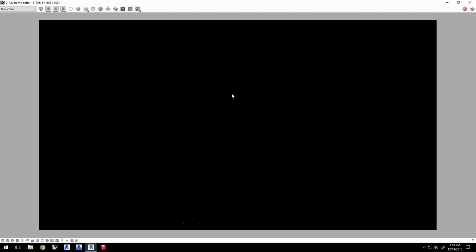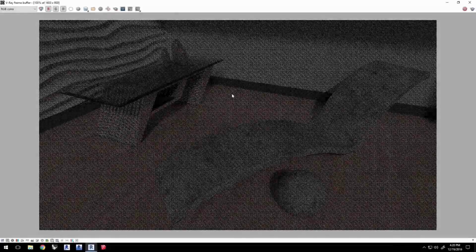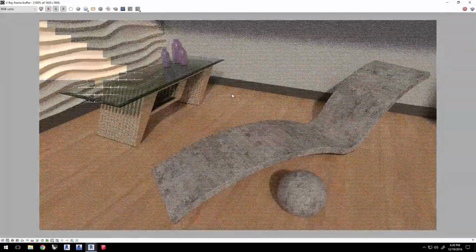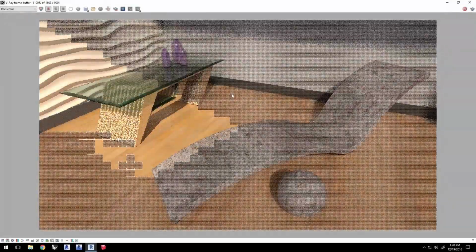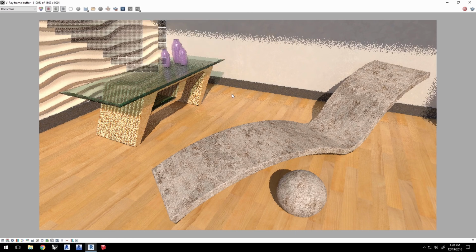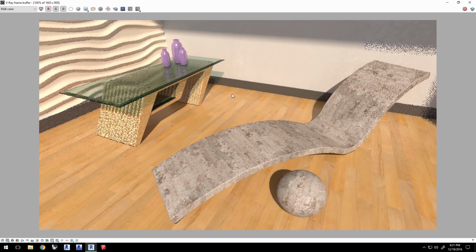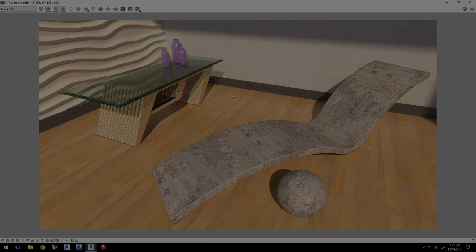As we elapsed the time for this render to resolve, we saw that by using the triplanar texture, we were able to create a more seamless material for the concrete chair, as well as a nicer plywood for the table. And displacements allowed us to create a dimensional look to this feature wall without needing to model the geometry for that effect. Thank you for joining us for this quick start video on more advanced material workflows in VRay Revit.